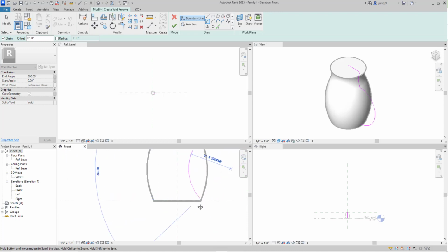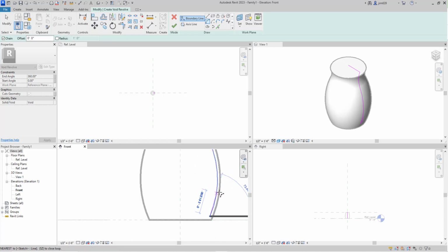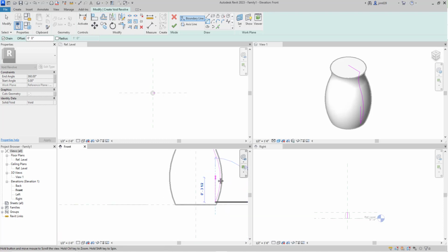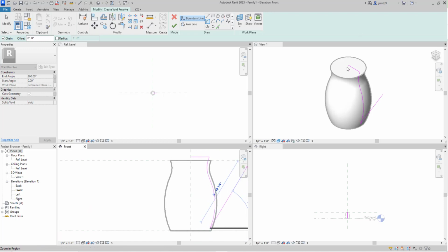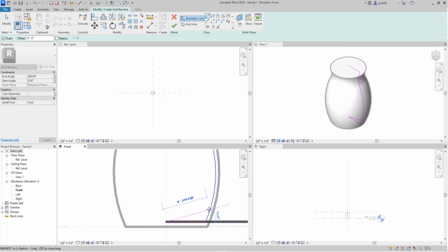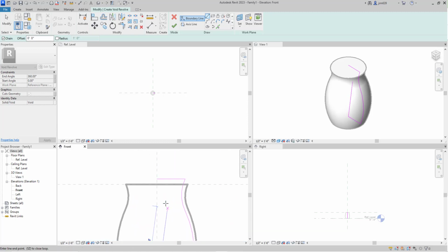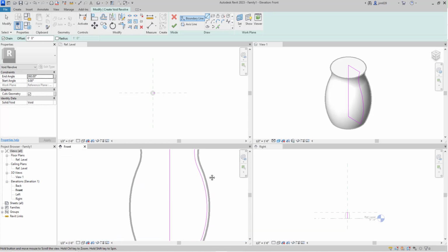And then you can come back and zoom out and see how you can get that form to go. And it's a little thin around the edges, but really the only effect that I'm looking for is that when it's in 3D I can see the hole. It doesn't really matter what's happening inside the vase. So I'm going to go ahead and click on the line tool so that I can draw the bottom. Remember, we're giving the bottom a thickness, and the thickness is really between the pink line and the dark gray line that we have there. And just like we drew the vase, I'm going to create a closed shape.